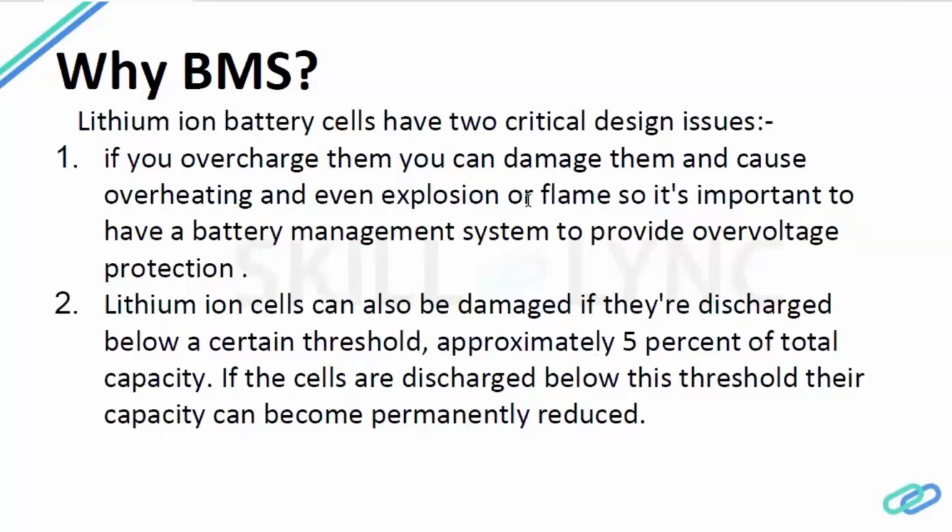For using lithium ion cells, we need to check two critical design issues. First, there should be no overcharging of the battery. If you overcharge the lithium ion cells, you can damage them and cause overheating, and this can go up to an explosion. So we can't overcharge the battery. The second thing is we can't discharge the battery below a certain threshold. We can't discharge any lithium ion cells below that threshold, so we have to maintain the threshold.